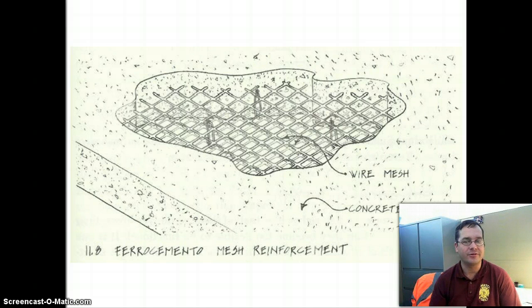So you might have a dome that's got a concrete roof thickness of 3 or maybe even 4 inches, something really small like that, and it's able to span huge distances, 80, 90, 100 feet. Very, very minimal material. And again, it's because we're using this material efficiently. Basically, every bit of material in that dome is stressed. There's no dead weight in the structure.